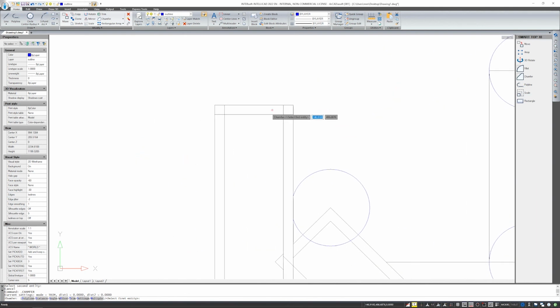Here I have a situation where these lines intersect, and I would like to simply shorten. I can choose the trim option and show this element, and those elements that are to be cut, but this is rather painful, so rather I would choose, for example, chamfer. Please note at the bottom in the command area I have information that on both sides 0 units are entered, so this cut will not be there. It means that it is just shown that these two elements and they're automatically cut to each other.